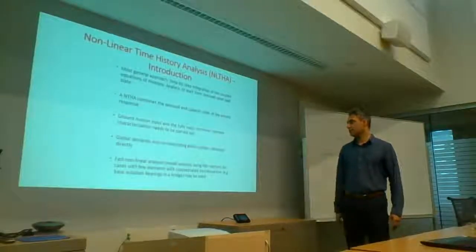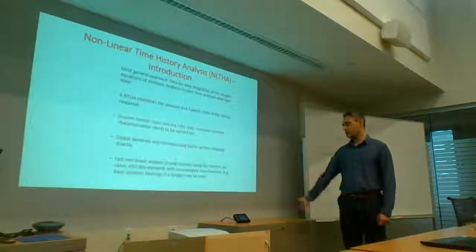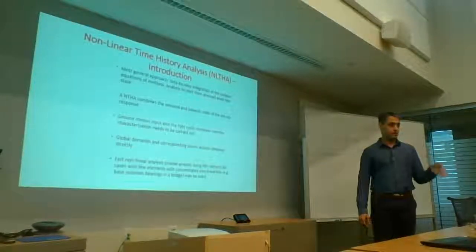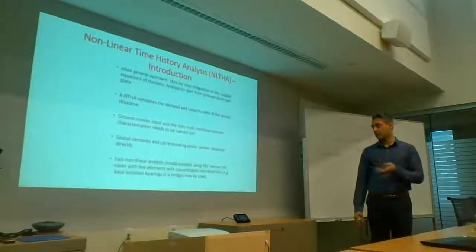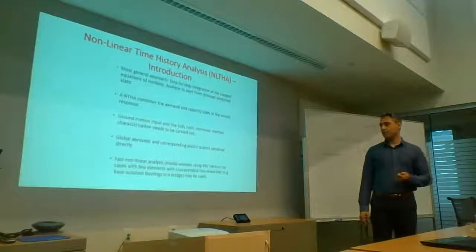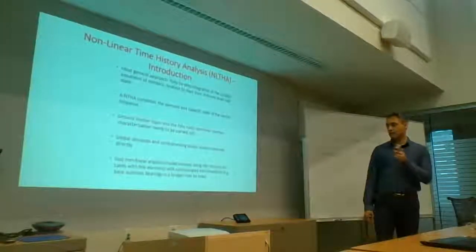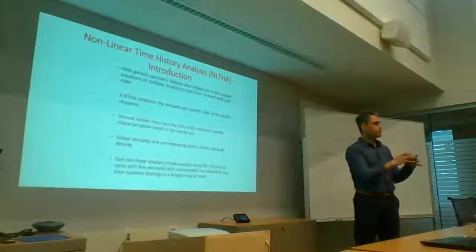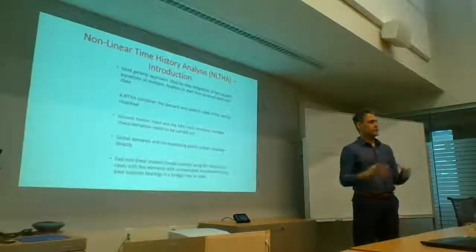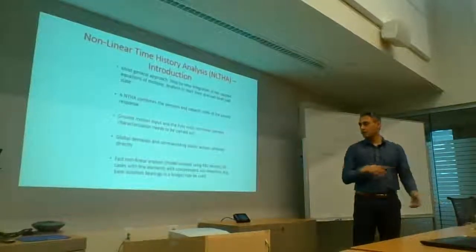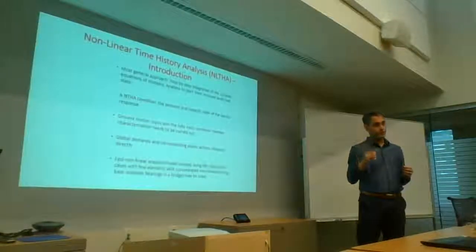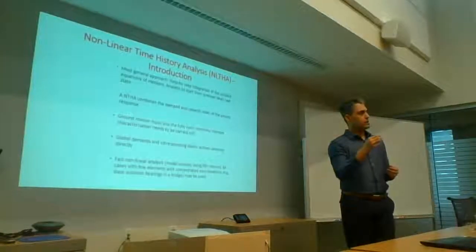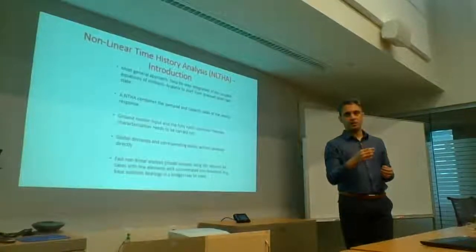There is this fast nonlinear analysis, which is a nonlinear modal analysis using Ritz vectors. Usually we use the natural modes for the basis of modal analysis, but you can also use Ritz vectors to come up with your modal analysis. And I think Dr. Ed Wilson came up with this fast nonlinear analysis technique. So if you have concentrated plasticities in only a few elements, there's a formulation. If you go to Google and you search for it, you'll find some stuff on it. There's a nice paper by Dr. Ed Wilson that I think you can get from CSI's website.